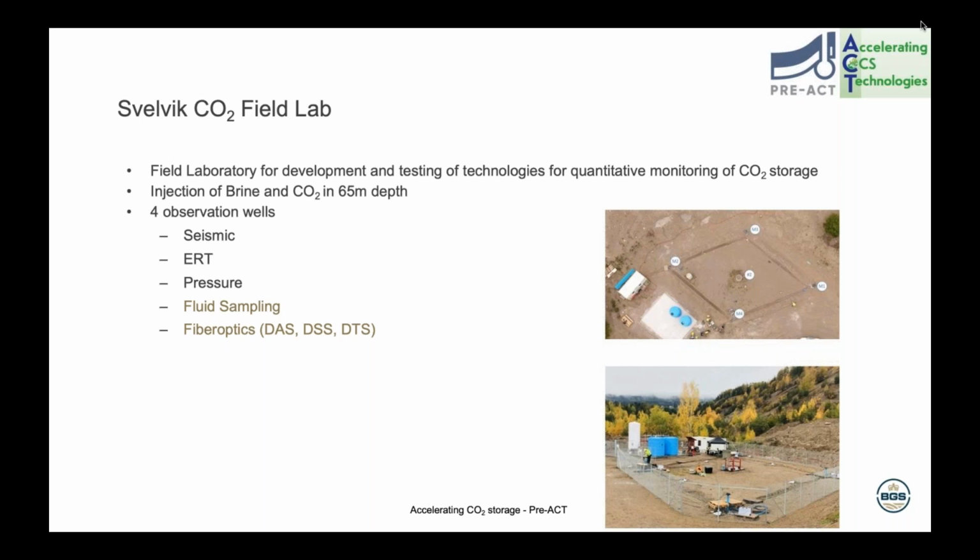So we had an injection well in the center of these 4 wells that you see in the image on the right, down to the order of 65 meters, and we injected at different times brine and CO2 to look at pressure and saturation variability in the subsurface, and how using our observation wells, which were instrumented for seismic, ERT, pressure, and also fiber optics and fluid sampling, how we could determine the response to each of these subsurface changes. And these were key in establishing both the site itself, but also in determining the new direction for experimental campaigns that are now being undertaken in the next phase of projects that are going forward.